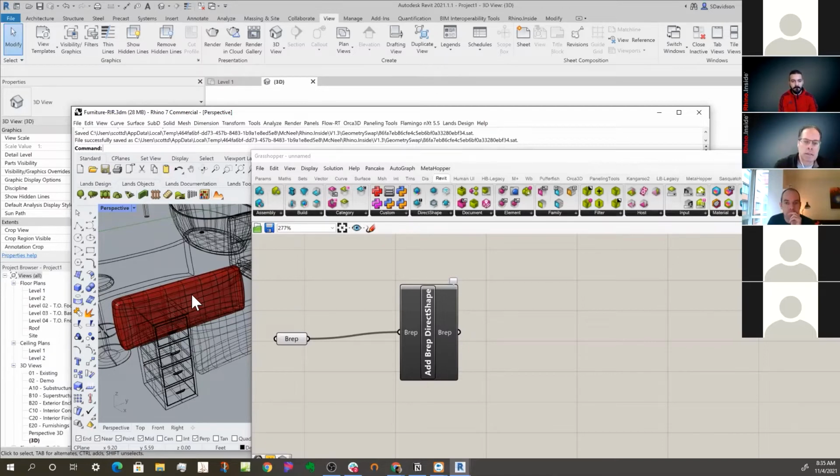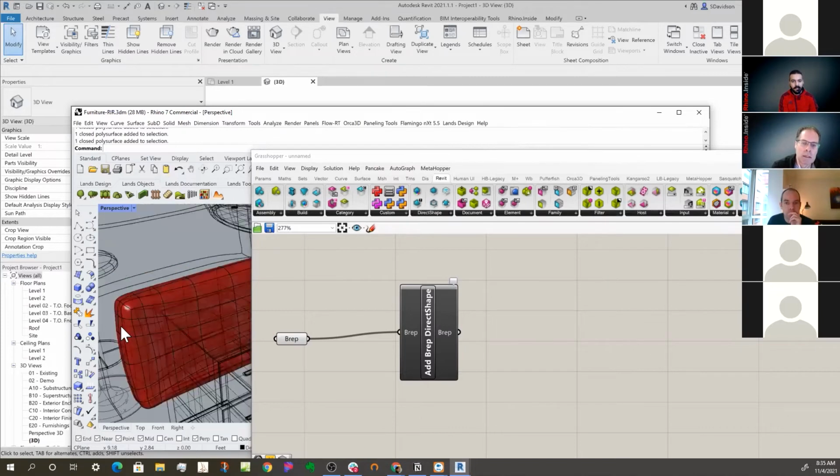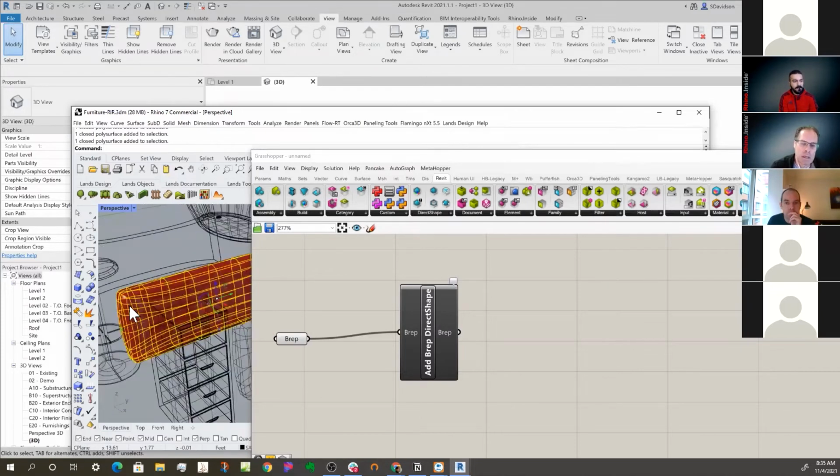It also means that there was something about this geometry that it rejected. The initial translation got rejected by Revit, and so we used SAT and that got across. So the piece to understand here is if you're seeing this use SAT a lot, it means your transfer is slow.